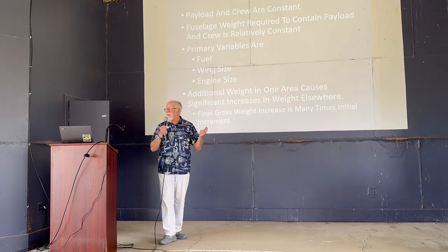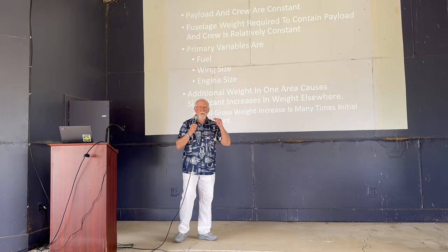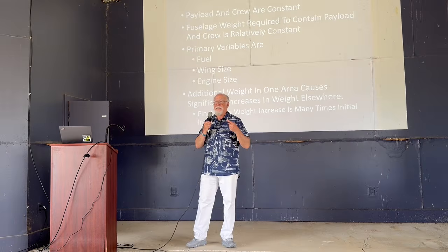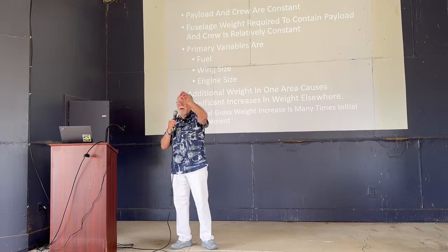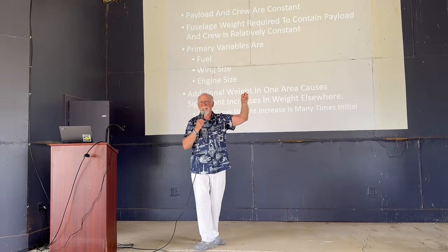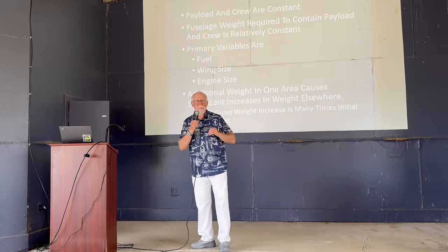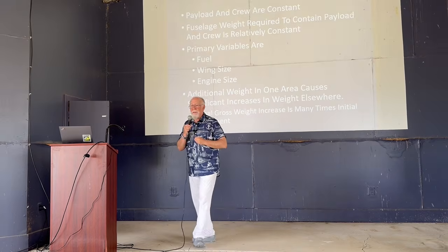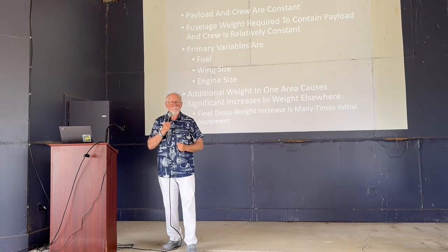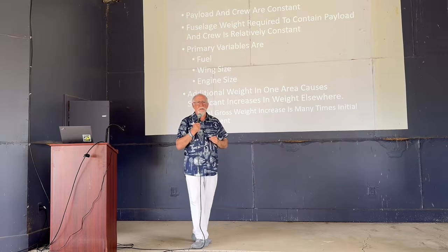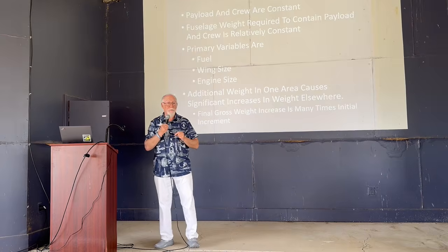Fuel, wing size, engine. The other thing you have to watch out for is there's this wicked cycle, which we call the wrap rate in weights. Every pound of arbitrary weight you add to an airplane increases the takeoff gross weight somewhere between 3 and 5 pounds. Because if you think about it, if I've got my airplane designed to carry your payload and you come with a 1 pound gold brick and say, oh, I want to take my precious brick with me too, I say, okay, I'll put the brick in. Gee, that means I need a little more fuel to make range, right? Okay, I'll add the fuel.